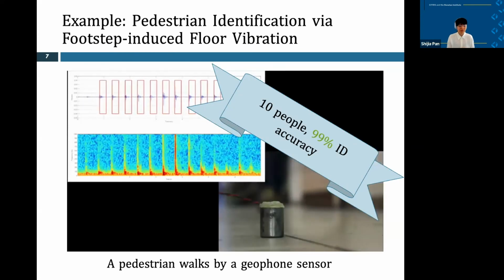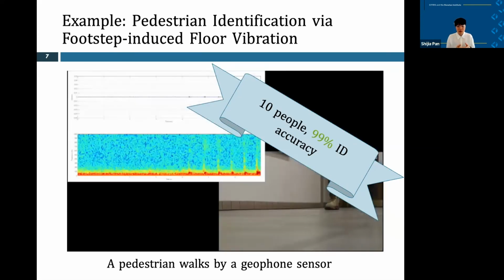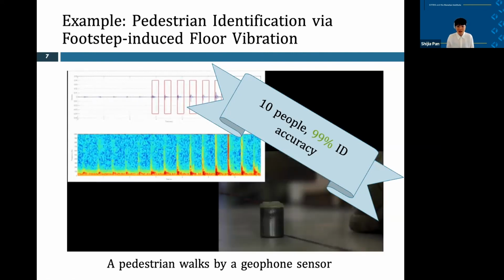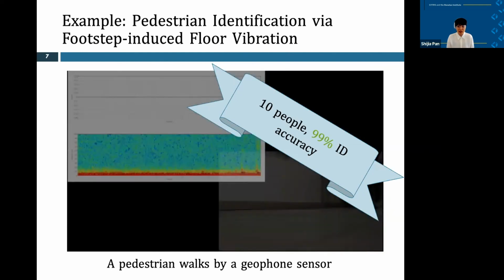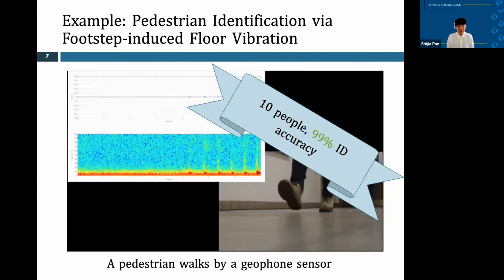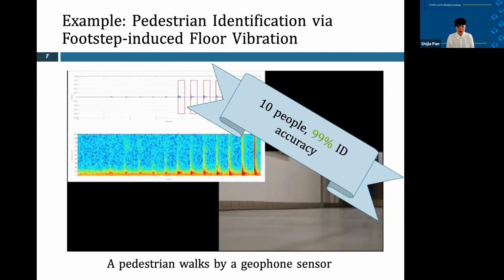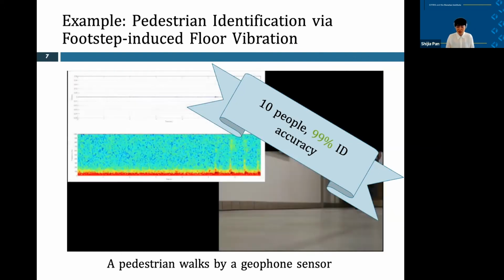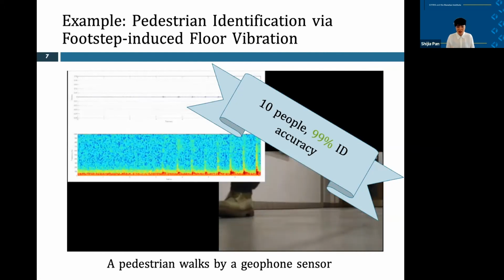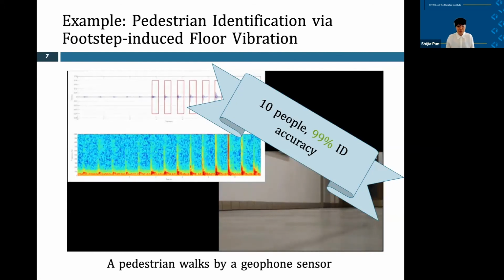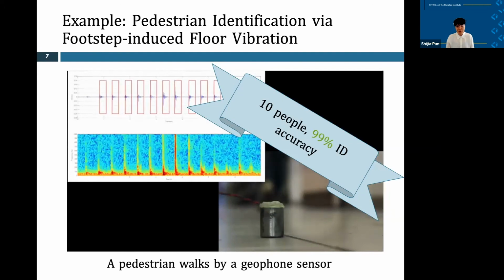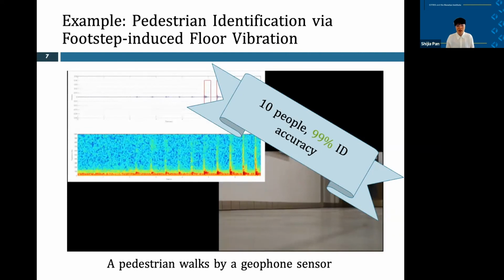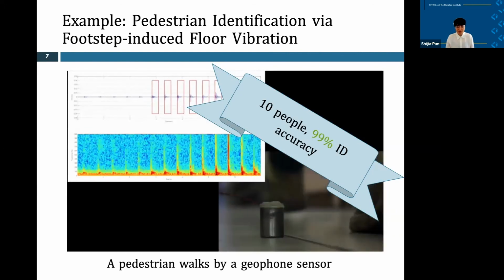So a lot of things in our structure would impact the signal acquisition. For example, if you accidentally place your sensor on a beam, then the beam itself might not vibrate a lot, or your building has certain damping mechanisms that reduce the amount of vibration humans can induce.